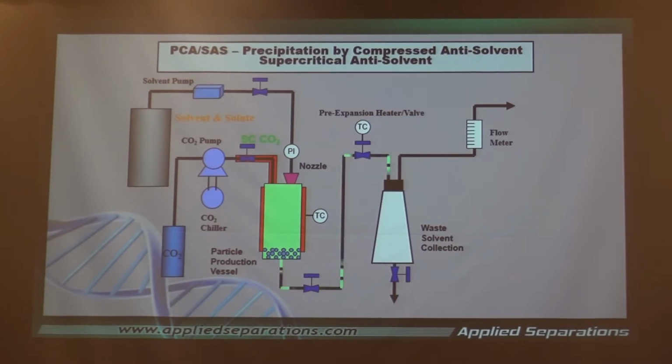There is not enough solvating power in the original solvent anymore, so you get a case where now you don't have enough solvating power and the precipitation will occur. Again, the amount of solvating power of the CO2 you can control by the density, that is, by the pressure. The tunability factor comes in again.